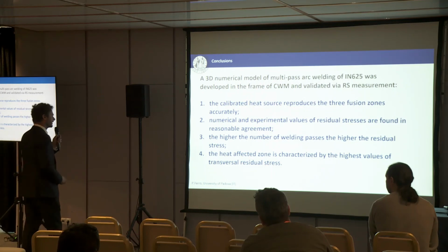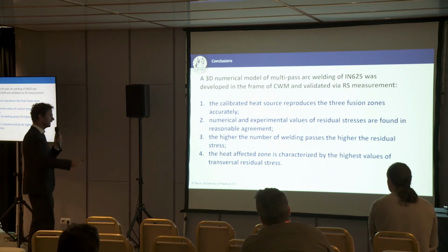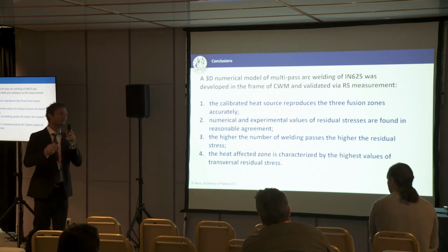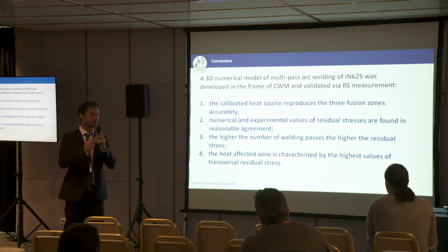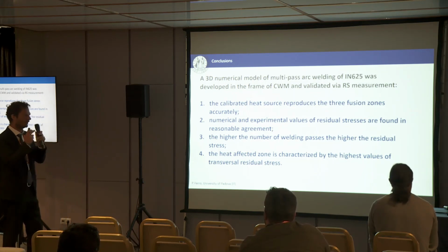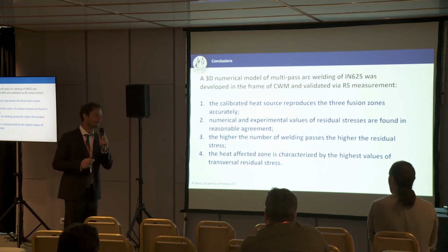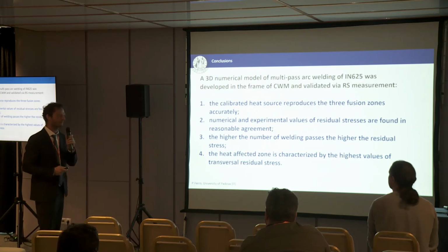At the heat affected zone, this is very interesting, very important in my opinion. The heat affected zone is characterized by the highest values of transversal residual stresses. And you know that in this area, in particular near the weld toe, the crack generally starts and propagates.